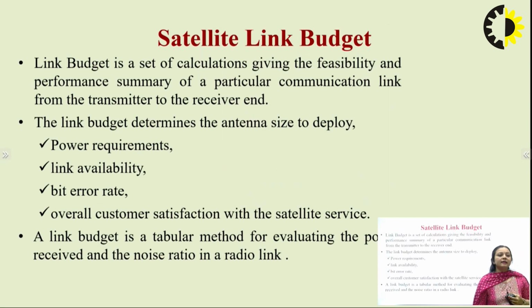So coming to the satellite link budget. Link budget is a set of calculations giving the feasibility and performance summary of a particular communication link from the transmitter to the receiving end. So the link budget determines the antenna size to deploy, or what all other things it can deploy, like the power requirement, your link availability, your bit error rate, overall customer satisfaction with the satellite service.